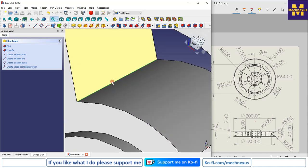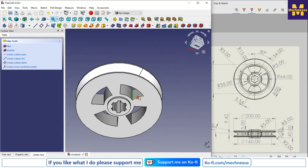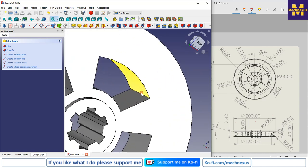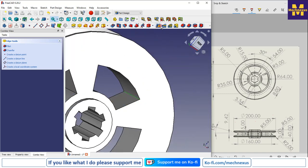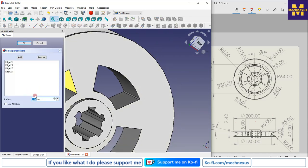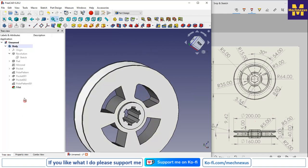So I will select this edge, this, and last one, and fillet 5 mm. Say OK, and let's see to pattern this fillet.